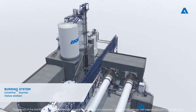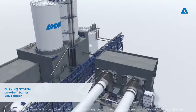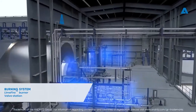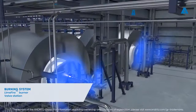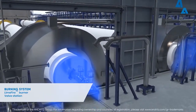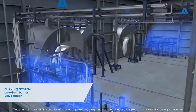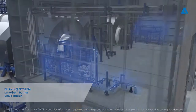To make all this possible, it is necessary to have a burning system. A burner is located at the firing end of the lime kiln and provides the heat for calcining the lime mud. There are various different fuels which can be used for burning. The burning system consists of burners for selected fuels, fuel handling, ignition gas handling, compressed air and steam handling, as well as flame control and safety systems.